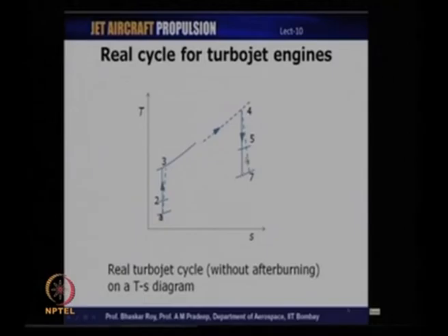We will also see the cycle diagram for the turbojet with afterburning, which is basically a reheat after the turbine expansion. Now, to carry out a cycle analysis of such a system, there are certain parameters which are fixed, or which are design parameters. Using some of these known parameters, we would calculate and determine the other parameters required for calculating the thrust and efficiency developed by this particular engine.